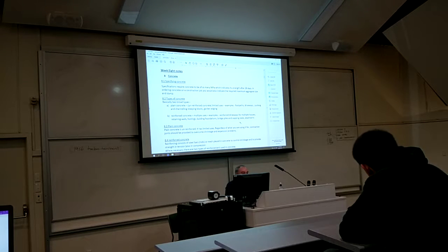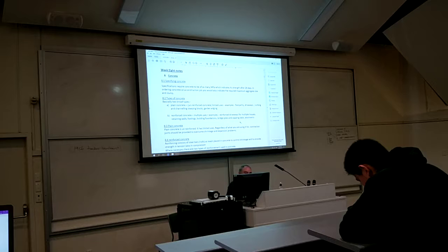Next question in the test is the difference between plain concrete and reinforced concrete. Where would we find each of those? The answer is plain concrete will be found in places where it wasn't that important to reinforce it. So you could have footpaths and limited driveways. You wouldn't want to put plain concrete where you're going to have trucks. So if you think that trucks are going to come in there, you need some of that mesh or some form of reinforcing. Curb and channeling is done without reinforcing. Stepping blocks, that should be stepping blocks, not steeping blocks, without an edging.